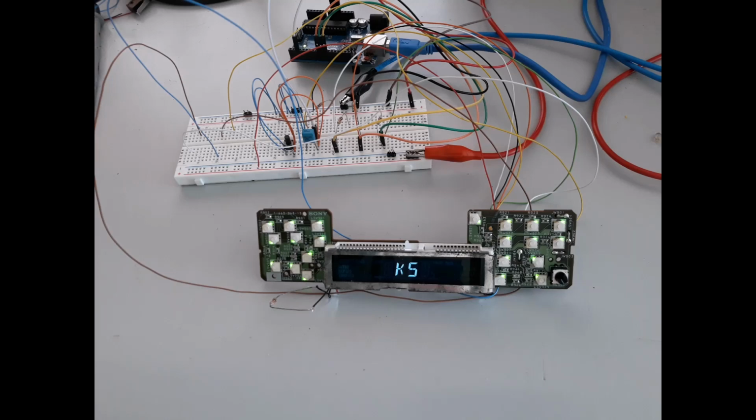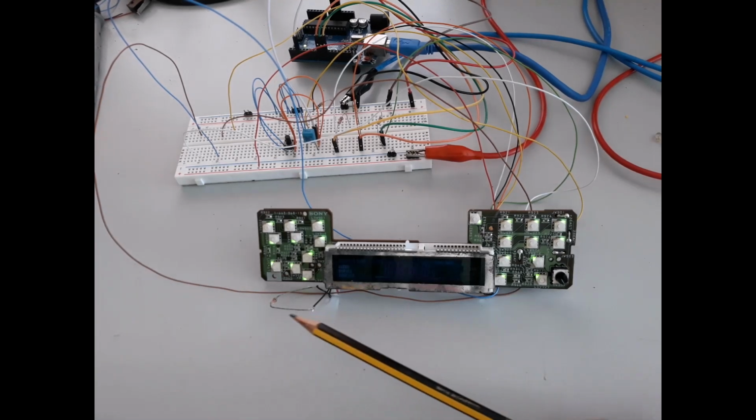The panel used 2 lamps for backlight which were burned out, so I had to replace them with 2 SMD LEDs so that they could enter the space reserved for the lamps. The serial resistor of 1K is visible here.